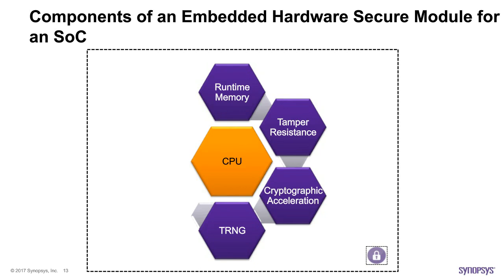Secure clock is another important feature for the applications that require an expiration time. This feature can only be effective if the hardware secure module has access to a clock that cannot be tampered with. For example, applications allowing limited time access to some resource such as movie rentals.